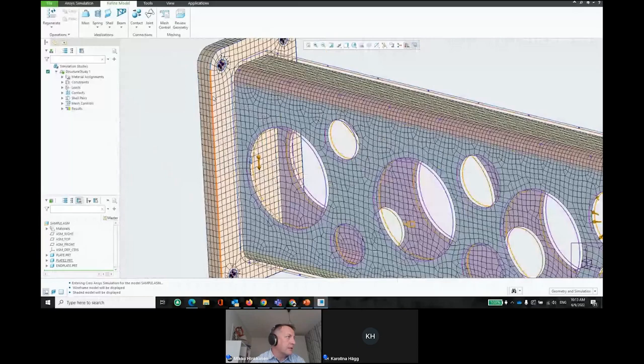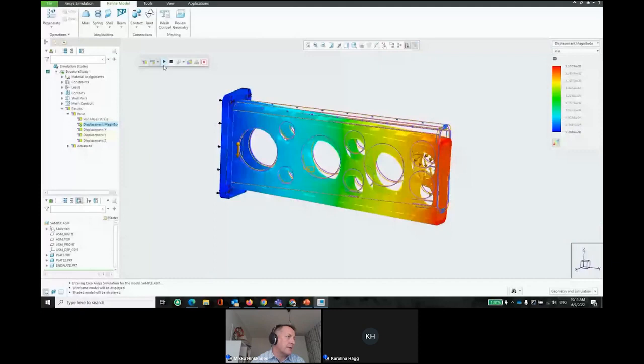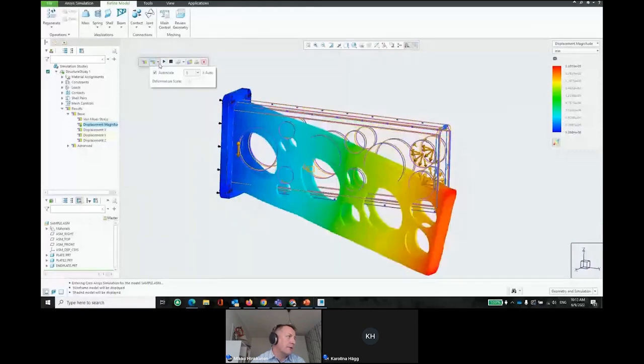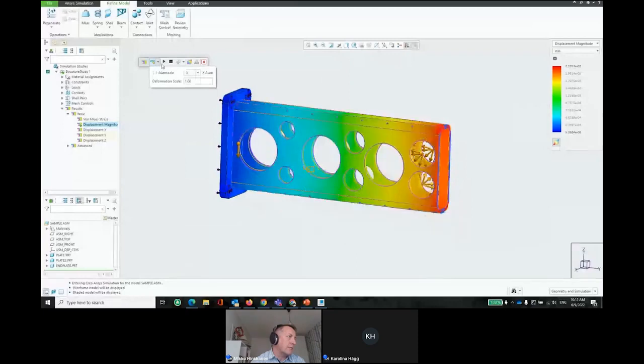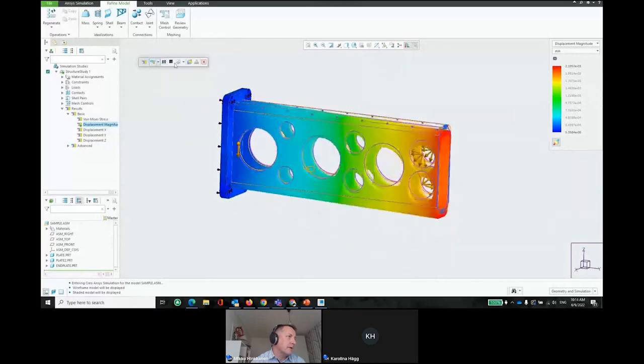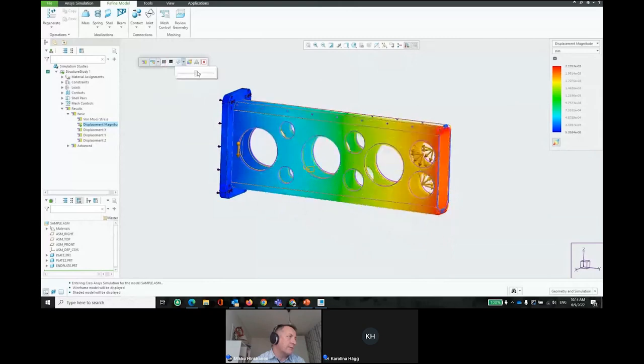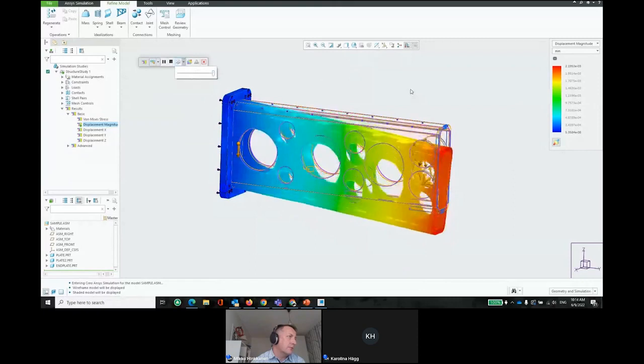And when you go to results, let's go for displacement, just activate it. This is already pre-run, and you will see that we have our deformations. If you want to scale your deformation, let's say 5 times, you really get a deformed structure here. I don't want to have the auto scale on here, I just want to play it back and forth. Let's put something like 2 times and try to play it. You will see that it gradually goes down, and we can also adjust the speed of it with this one. So there are some new tools for you to play around with.